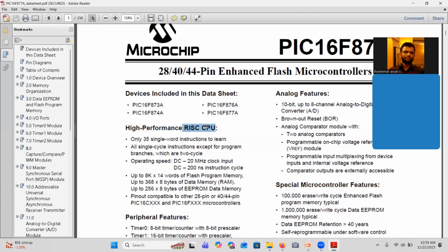And then the process for which we use the microcontroller. Based on that, we will decide whether we can go for 20 megahertz for the ADC, and what the operating speed can be. If we are using a timer, do we have to pre-scale the timer to some extent, or can we use it as such? Those decisions will be taken by the embedded programmer. It depends on the project nature and project requirement. According to that, they will decide.